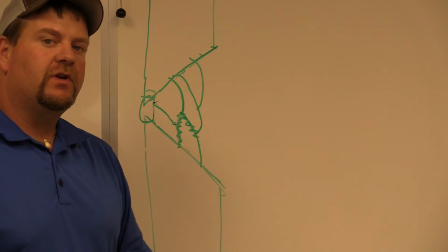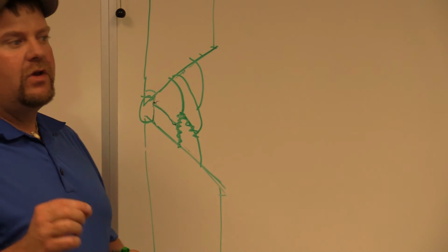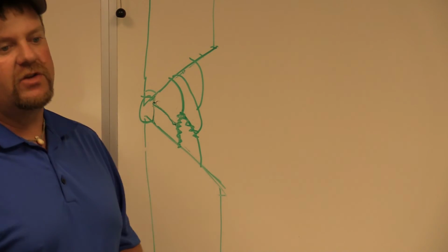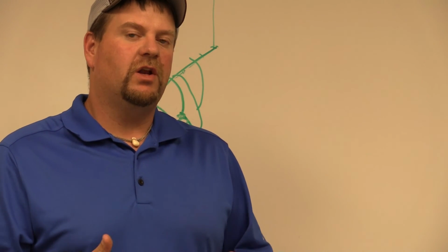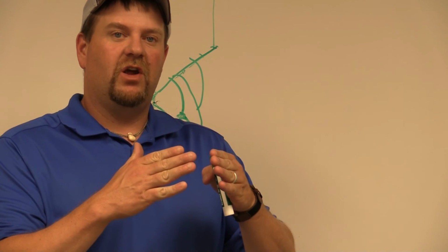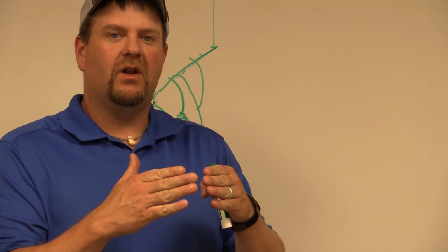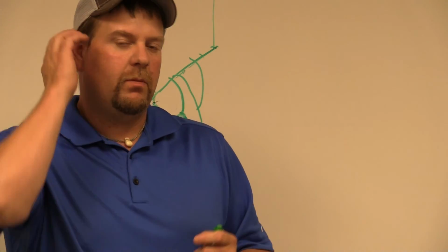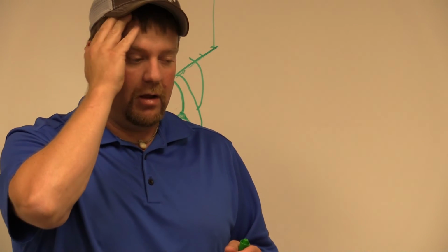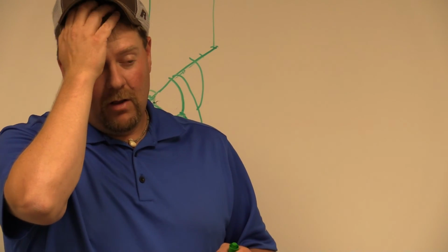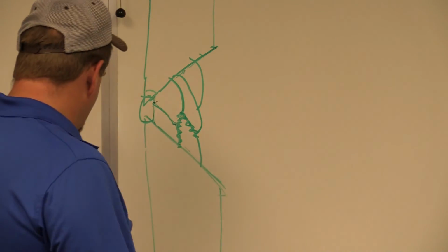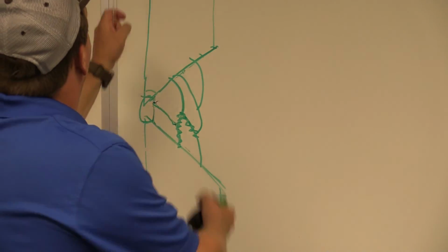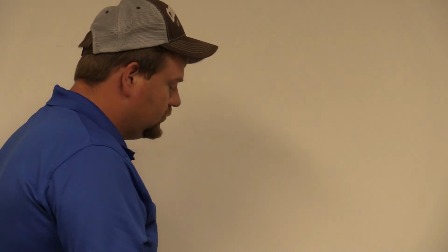Now this is on thicker material. On really thin material, say up to 3/16 of an inch for the most part, we're going to be able to do it all in one weld bead or one pattern. It also depends on what the weld joint is. If it's an edge joint, then yeah, we're going to get the whole thing in one pass more than likely. We may not even have to do more than one pass or a multi-pass weld, okay? That saves us a bunch of time there. But yeah, we start looking at the essential variables, what we need to do, what's important, and so forth, okay?